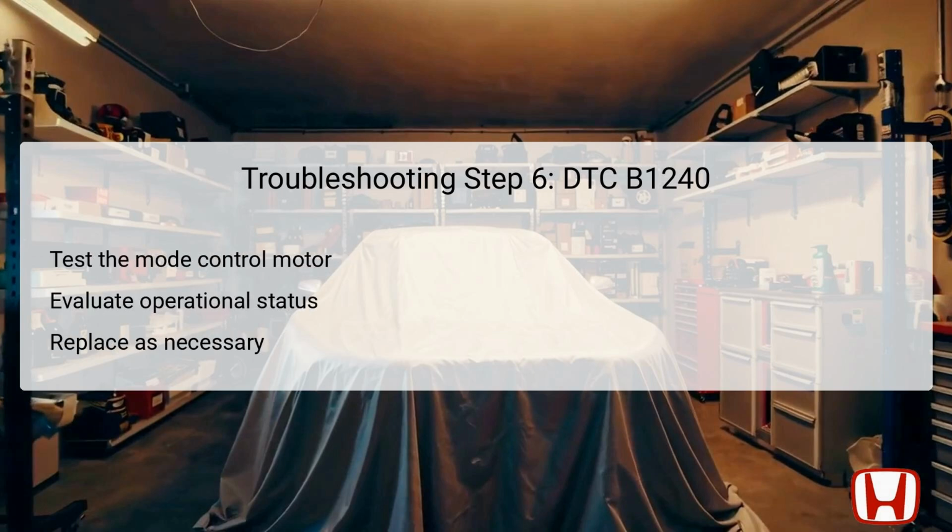The final step involves testing the mode control motor itself to determine if it is operational. This consists of supplying power and observing the motor's response. Should the mode control motor function correctly, it confirms that the issue likely lies within the climate control unit itself,